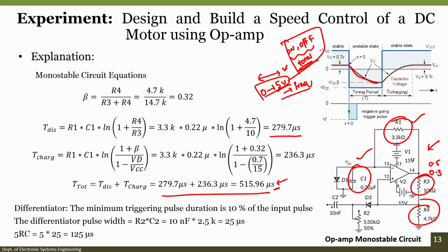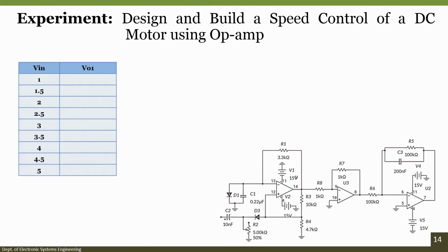So, with this understanding, after conducting an experiment yesterday, we understood that for the whole range of input voltages to the motor, which is 0 to 5 volts, the encoder changed its frequency from approximately 227 Hz to somewhere around 1.5 kilohertz. For all these frequencies we understood that the monostable multivibrator is working fine and as per our